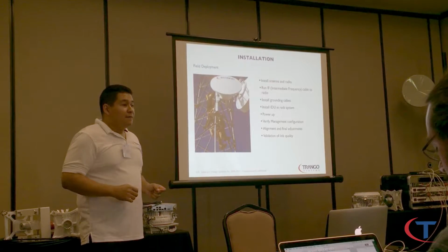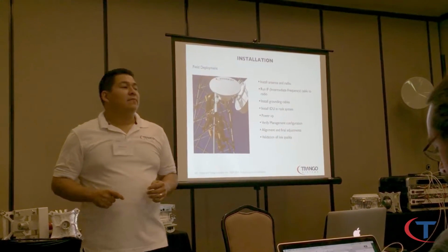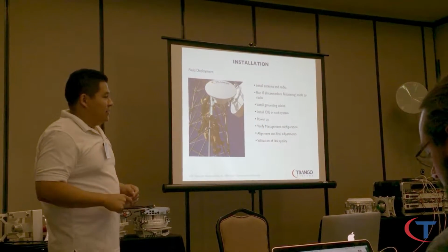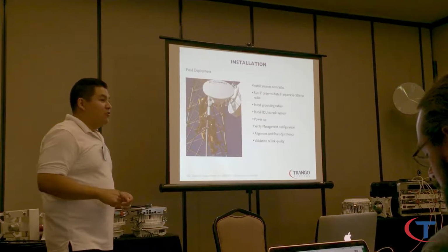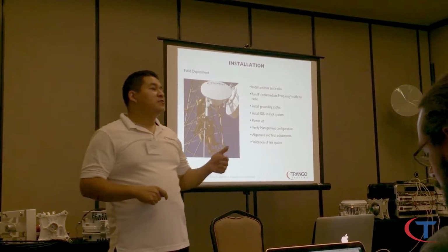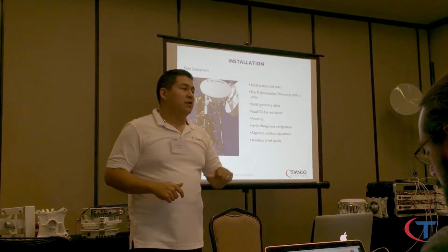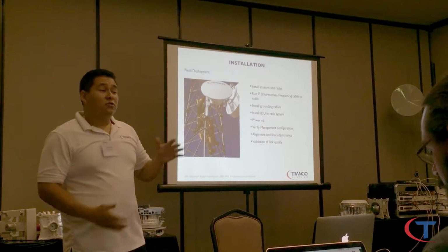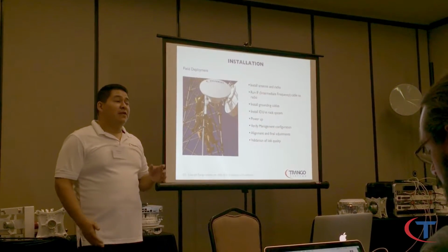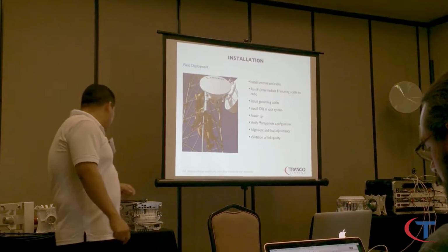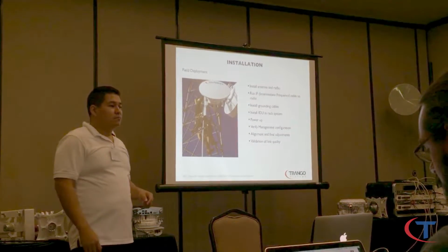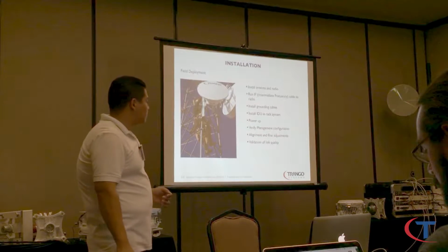You install ground kits and polyphasers, or just polyphasers that are grounded? Well, in general, grounding, we want to talk about polyphasers at the top of the tower and before the shelter. And if the run is long enough, if it's 75 feet along the tower length. Okay. And I'm going to actually show you guys an inline grounding as well, which is what you want for the other line. So, yes.